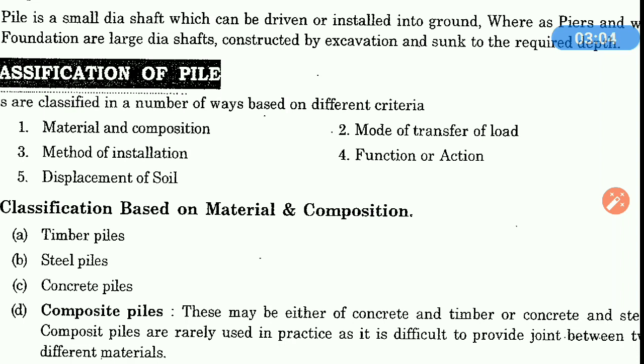Not in all cases does the pile have to transfer load from the column to the hard strata, and in most cases foundations have to undergo compressive load. But in the case of pile foundations, sometimes they may be subjected to tensile load, etc. So we will later discuss how to classify based on function or action. And then fifth is the displacement of soil. So let's begin. First is the classification based on material and composition.